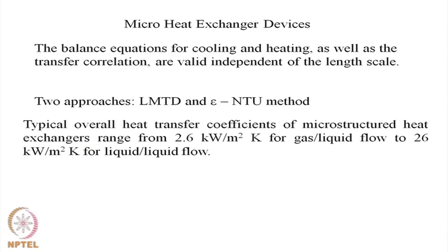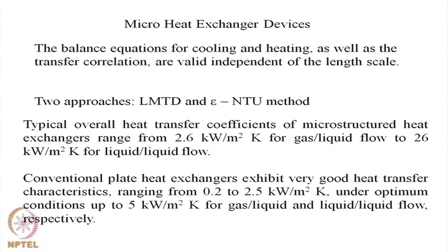There are two different approaches while designing a heat exchanger, the LMTD method and the epsilon-NTU method, and either can be followed depending on the situation at hand. Just to give you an idea of the typical overall heat transfer coefficients of microstructured heat exchangers, they range from 2.6 kilowatt per meter square for gas-liquid to 26 kilowatt per meter square for liquid flow.